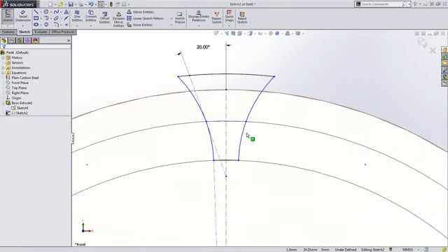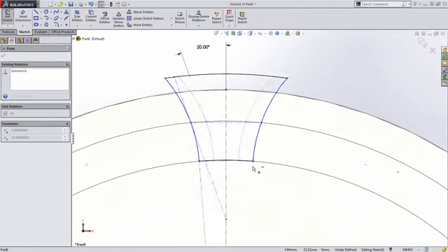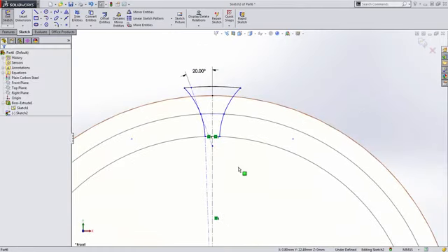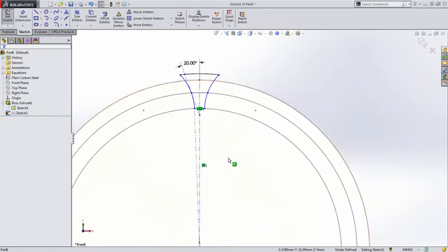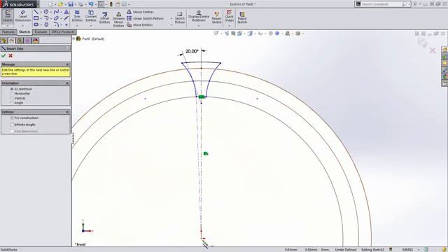So a few other pieces of information are missing. You can see that we're able to expand this, though the profile is pretty much holding its own. This is because we need to incorporate the number of teeth into our gear. To do this, we could do a calculation to solve for the chordal width of this cut, but I'm going to do this using some sketch geometry.